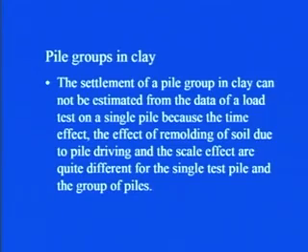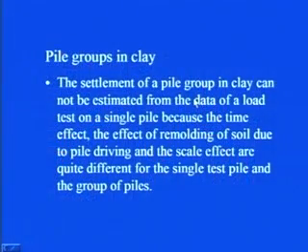See what happens in case of clay: when you install the piles, the clay gets remolded, and it is with time that it gains its strength. In case of an individual pile, the disturbed area of the soil is less as compared to that in a pile group. So, that is why you cannot estimate the settlement of a pile group from the data you get from a single pile load test.